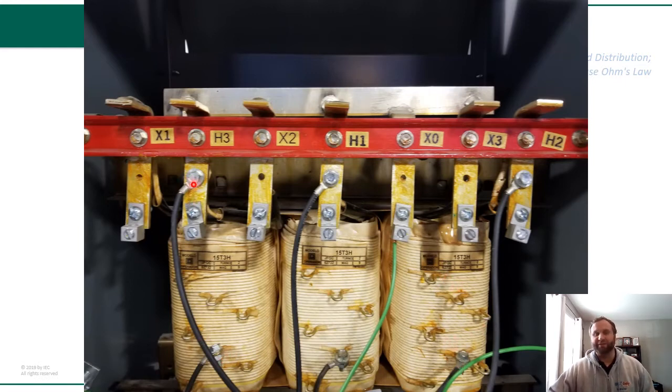Right now they're factory set in this drawing so that the input voltage would be exactly 480. But if we had an input voltage that was closer to 500, we would move these taps all the way to tap number 1, which is down here. I'd move this tap from tap number 3 to tap number 1, so that my turn ratio would change, allowing me to still get 120 volts on the secondary side.